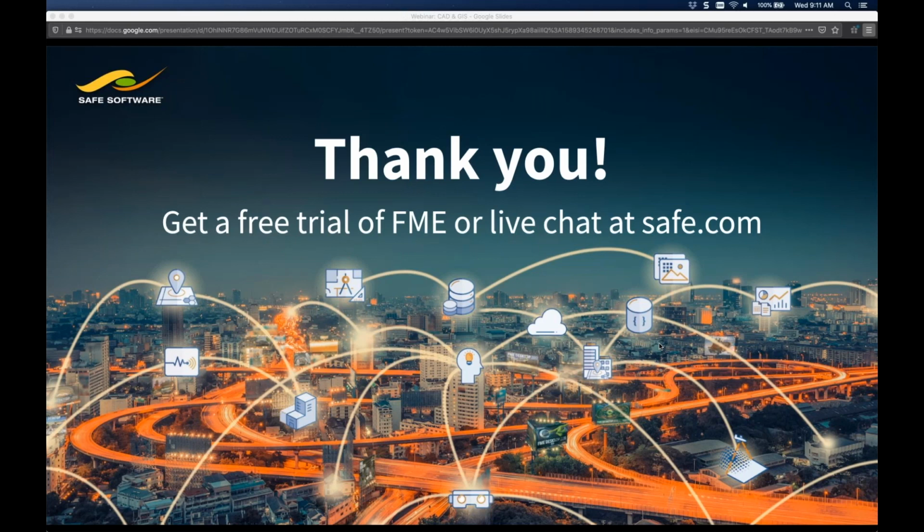So this is what people have asked. FME itself does not provide an interactive tool to help you sort out the coordinate system of an unknown CAD file. I will say that our friends over at Esri have made a really nice tool. I don't remember what it's called, but there's a tool inside of ArcGIS that you can grab onto a CAD file and drag it into the right spot against a base map, and then it will write out a .wld file, and FME will honor the WLD file. In Esri as well, you can write out a .prj, and FME will honor that if we pick it up. And if there is a coordinate system inside there, we will honor that as well. We can read those out of AutoCAD files if they're modern and they have a coordinate system.